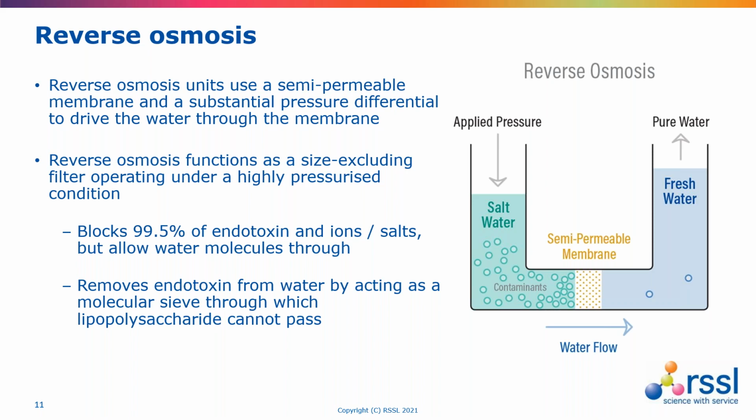And this is where the term purified water comes from, because it's a reference to its chemical properties in terms of the trace levels, organic carbon and conductivity. And often these systems exist in a series, so water might pass through one RO unit and then a second RO unit and so on. And we're really creating this kind of molecular sieve-like approach, and our removal of contaminants comes about through size exclusion. So we can separate out ions, salts, microorganisms, and so on.